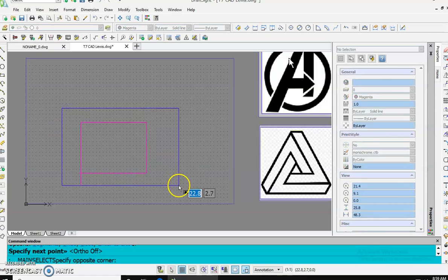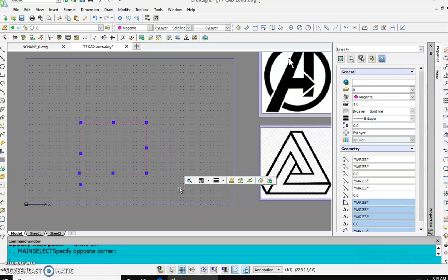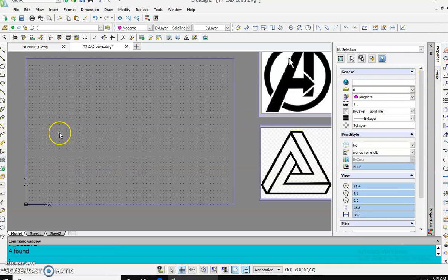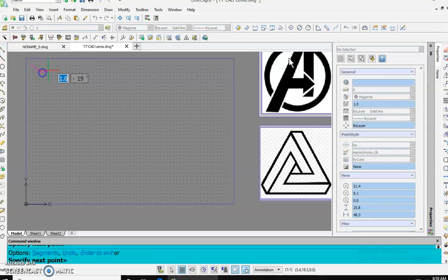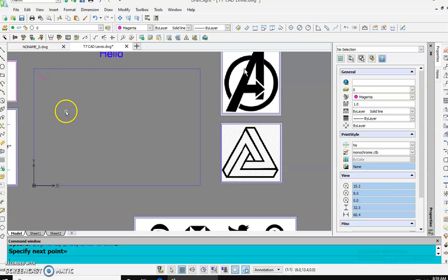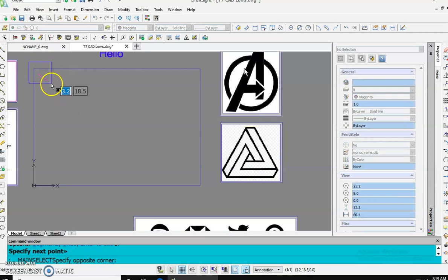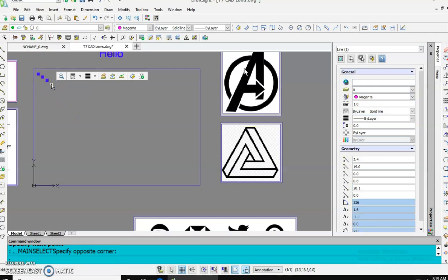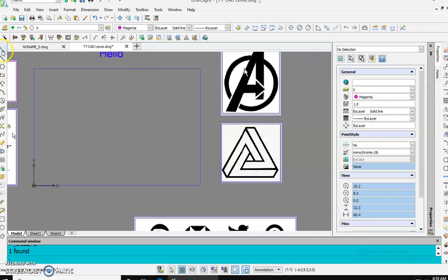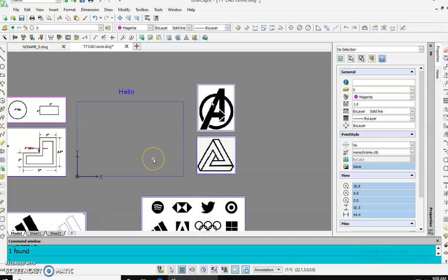So the first thing we want you to do here is just acclimate yourself with the program. Understand how to draw a line. Again, we said anytime you open up a new drawing, make sure you initiate it by just drawing a line that wakes up the program and you're good to go. Okay? Don't worry about saving anything just yet. Anything we're doing right now is just acclimating you, understanding where the line command is, understanding where the erase command is, and understanding what this Ortho is. It's very powerful.